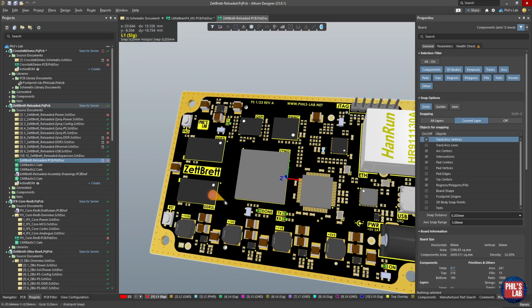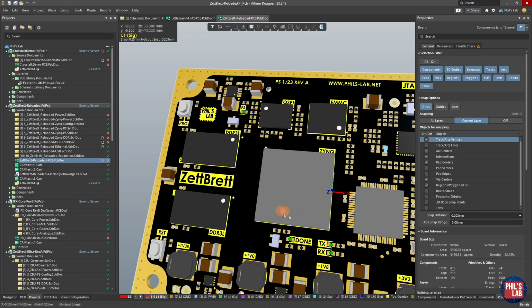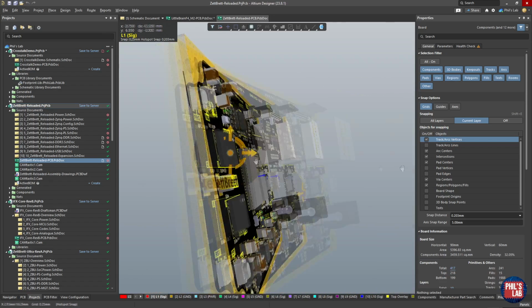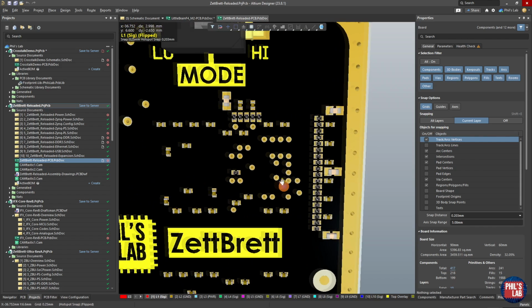Where I needed parallel termination, and where you generally do, is for DDR3 and DDR4 interfaces. In this case, I've routed this as a flyby configuration, meaning I route data point to point between the modules and the controller, but address, command and control signals I route from my host controller, which is the Zynq, to the first DDR memory module, to the final DDR3 memory module, and then I end this with parallel termination with these resistors scattered around the last device.